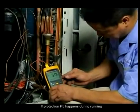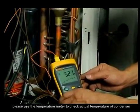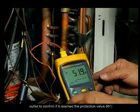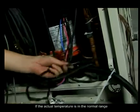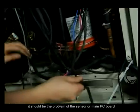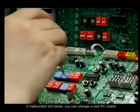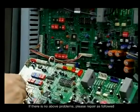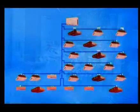If protection P5 happens during running, please use the temperature meter to check actual temperature of condenser outlet to confirm if it reached the protection value 65 degrees Celsius. If the actual temperature is in the normal range, it should be the problem of the sensor or main PC board. Please change the sensor at first. If malfunction still exists, you can change a new PC board. If there are no above problems, please repair as followed.